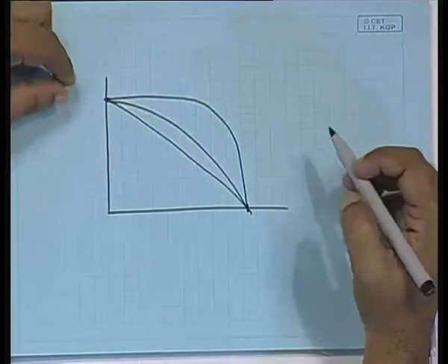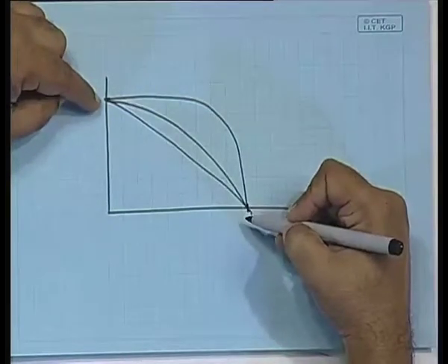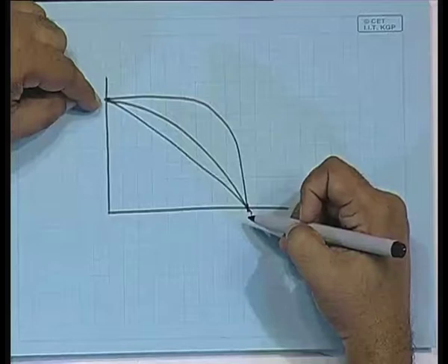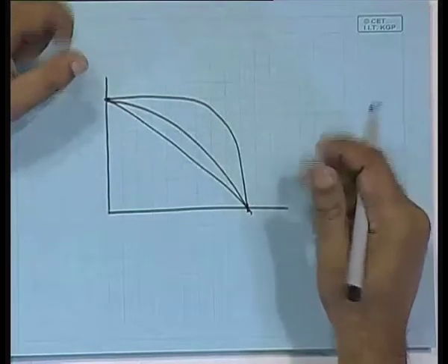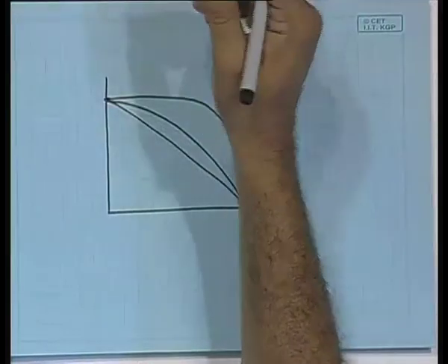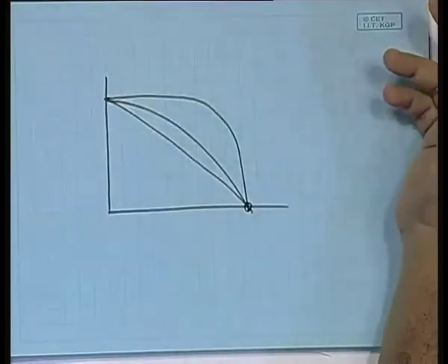In either case, the open circuit voltage and the short circuit currents are the same, and therefore, it does not suffice simply to say that this produces this much open circuit voltage. You will find that in many cases the photovoltaic panels are sold. If you just go to the market, you can get photovoltaic panels, and you will say that it produces 30 volts. An energy engineer should say it tells you nothing, because a photovoltaic panel's 30 volts is only here.